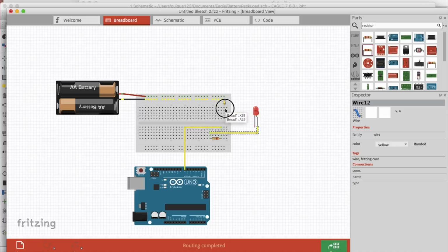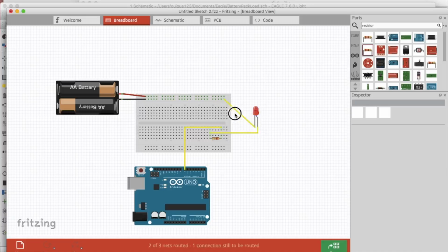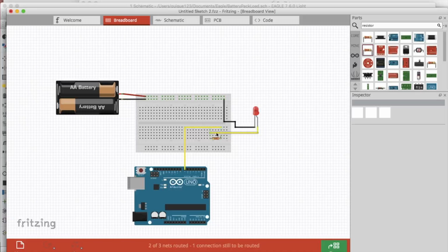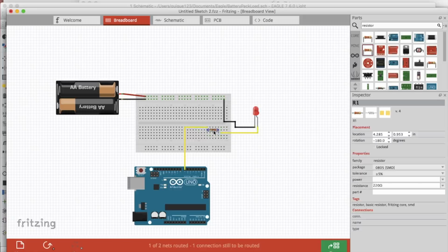so what we want to do now is we want to finish the circuit off. Let me just drag a few more here. This is how you add the bend point. You gotta make sure that you get that angular icon while you hover over the wire. It's not always there. Sometimes you gotta mess around with it and make sure that you're over the wire itself.